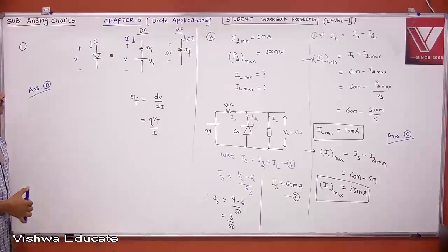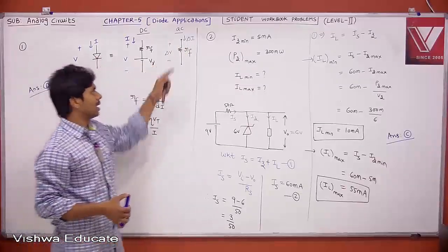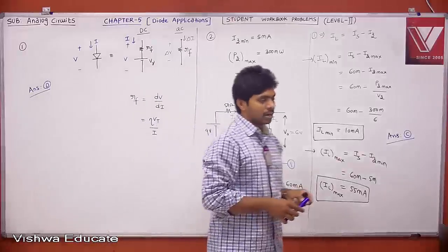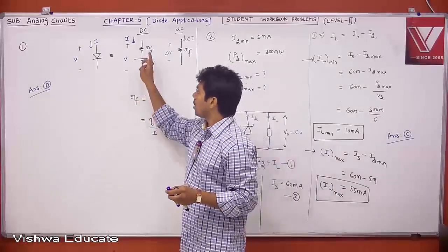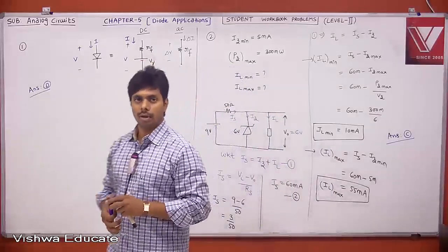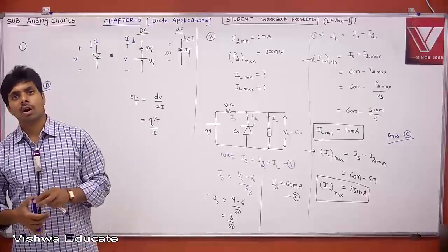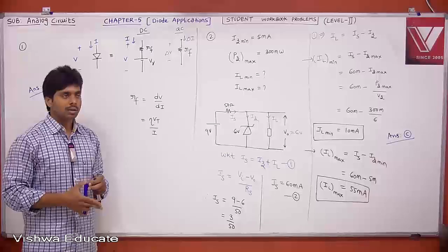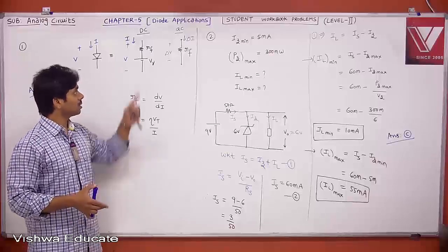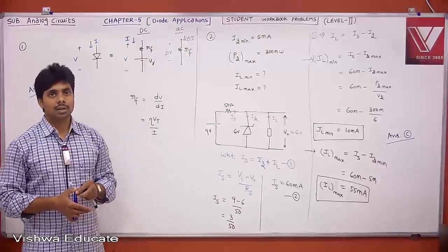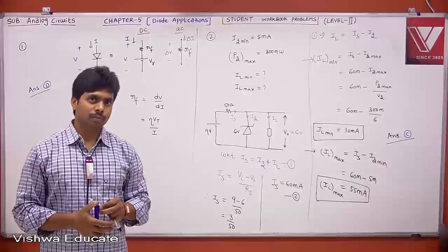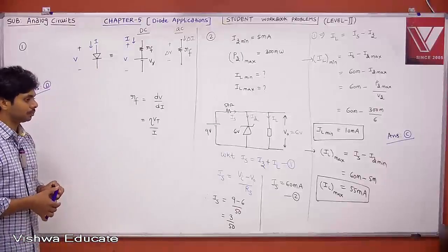That's why under AC condition, your diode can be represented as dynamic resistance. But under DC condition, you can represent it like V gamma along with on resistance. That on resistance can be fixed, then that is the third approximation. If that on resistance is derived from dynamic resistance, then it is almost equal to your exact model at that bias point.